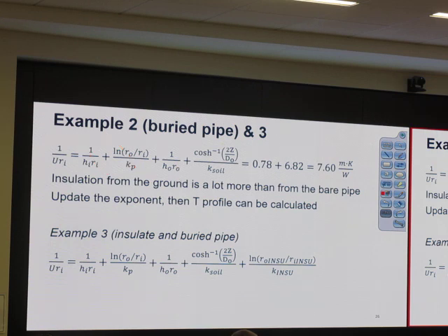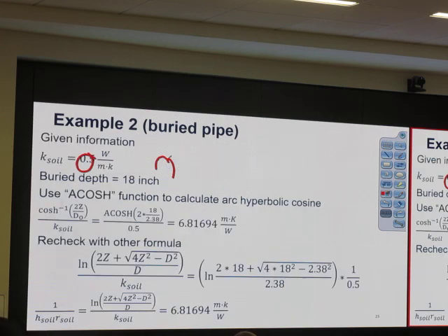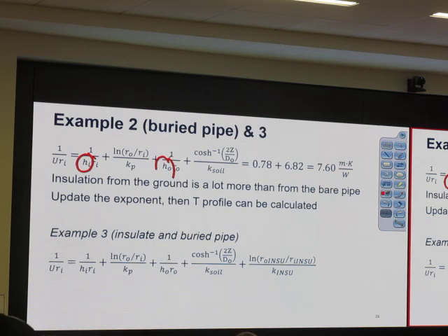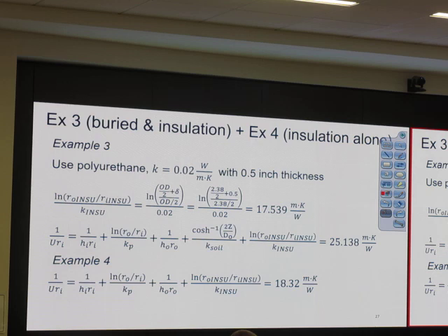Why do I have to mention this again and again? Because the step to calculate HI and HO is very painful. Okay, it's very painful. You see the formula, right? Gnielinski equation, external flow. Those steps are painful. We may just take that. Or the case where we insulate the pipe and bury it, you will see that sometimes the insulation layer is the only thing that matters. Okay?